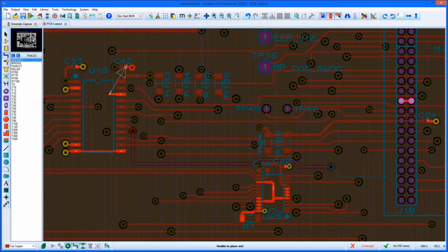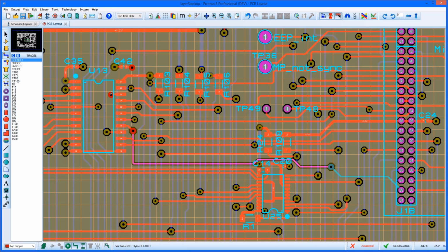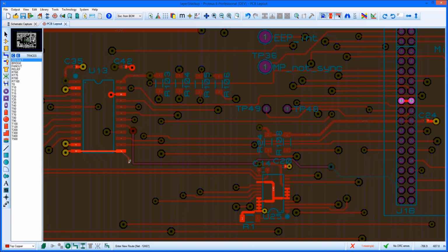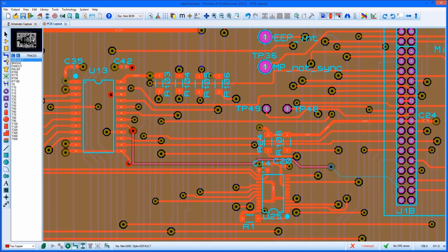Proteus also uses the Stackup information as an aid to quality assurance. For example, during the pre-production check, there are tests that all holes are on valid drill ranges and there are no tracks on plane layers. Finally, the layer Stackup information is also exported in the README file that accompanies the Gerber output sent to your board manufacturer.